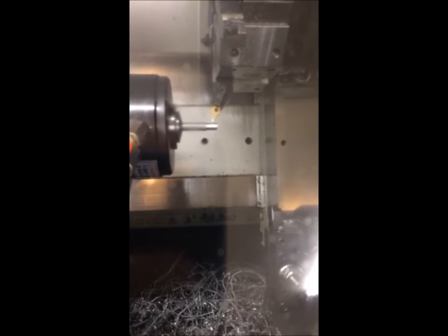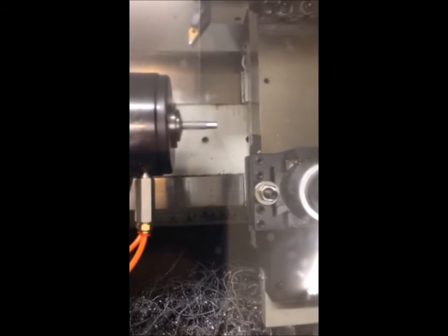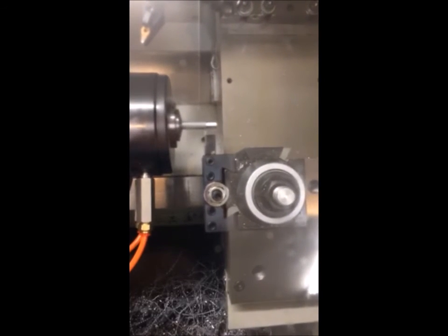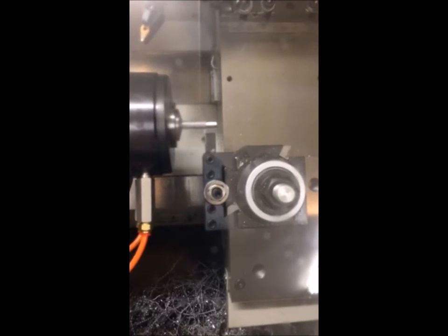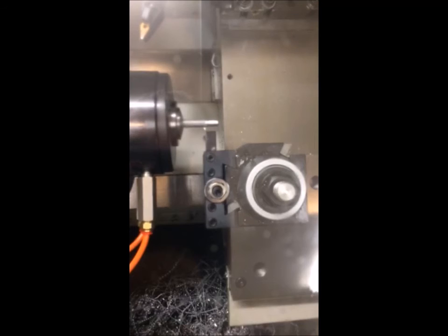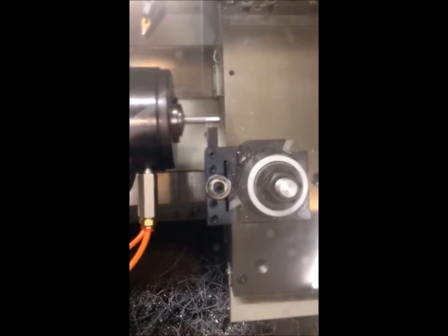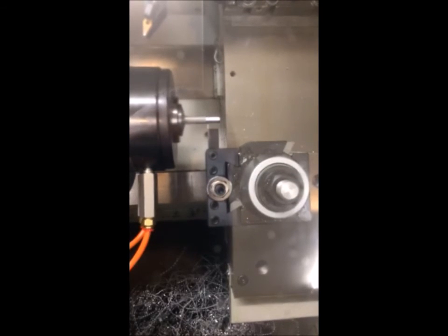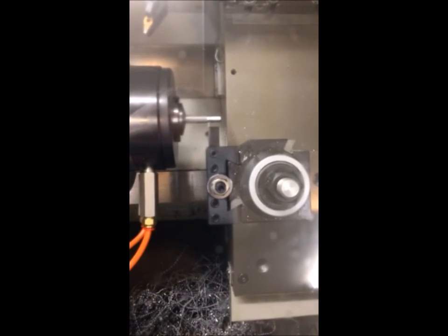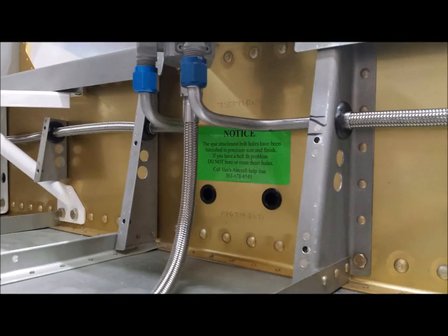Then it puts a little bit of an angled chamfer onto the end of the tube, and that just makes sure that there's no sharp edges and you have a little bevel in there. And then finally we do a tool swap, and now it's going to machine a groove, and that groove is going to be for the lock collar that slips over it once we put the flex hose assembly over it. So effectively what we're doing is we're pretty much duplicating a standard hose end assembly, but we're doing it in a very custom rigid tube, which allows us to create this combination rigid tube and flexible hose assembly.